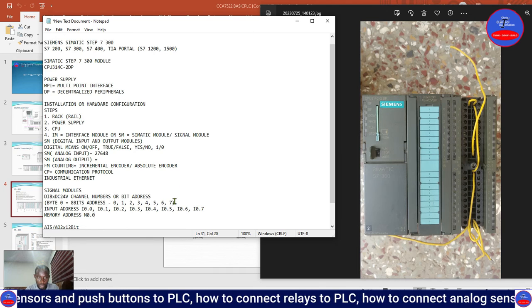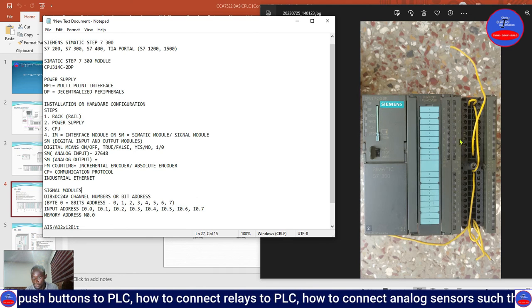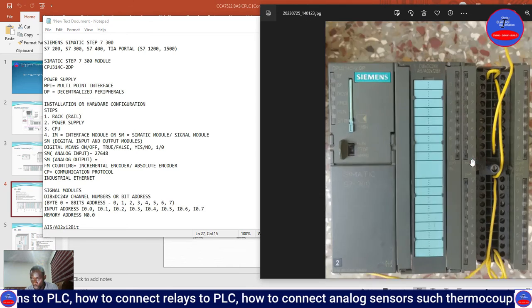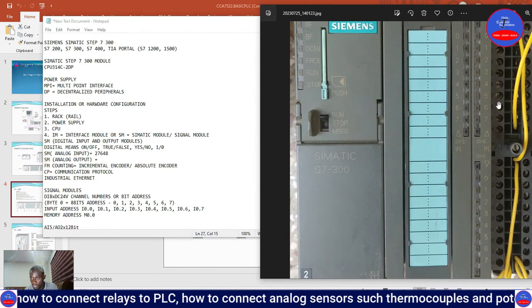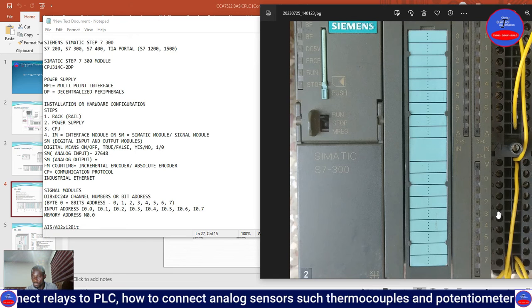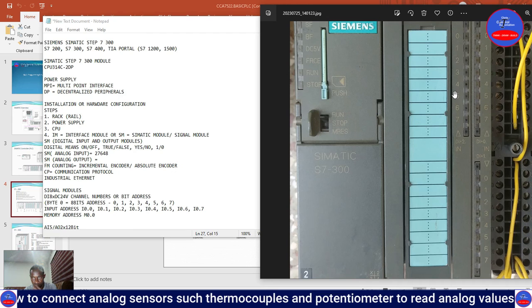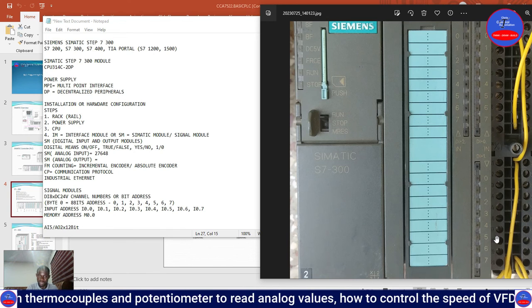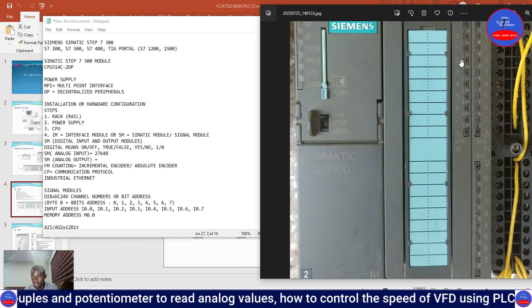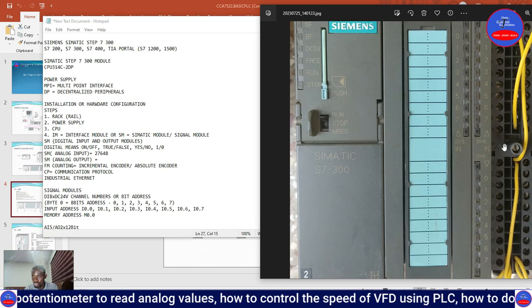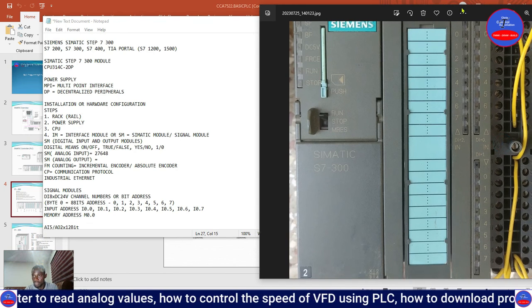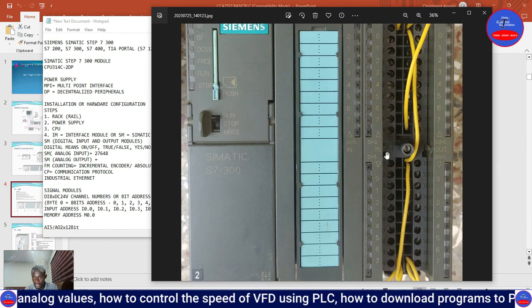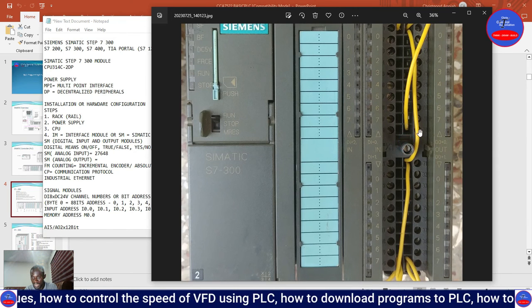So now you know your data input. The same thing is going to be here, this side, the whole of this block. This one is byte 1, byte 2, because we have only 3 input bytes: byte 1, byte 2, byte 3. But when you are counting and programming them, it is byte 0, byte 1, and then byte 2. So these are our input bytes, and then these are output bytes.